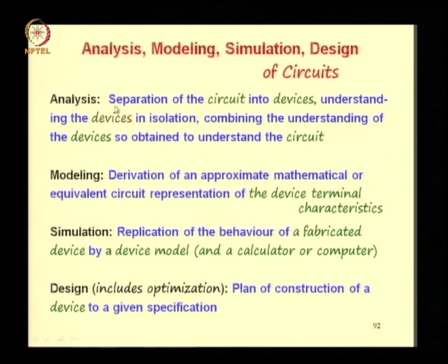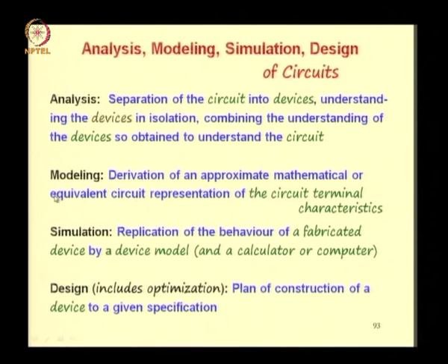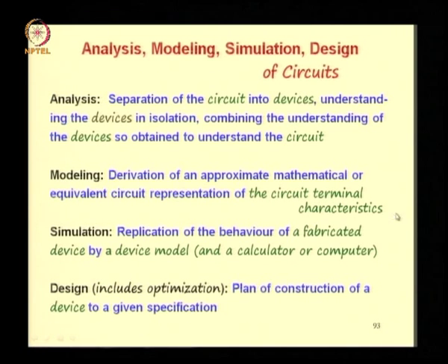So circuit analysis is separation of the circuit into devices, understanding the devices in isolation, combining the understanding of the devices so obtained to understand the circuit. In modeling, you replace the word device by circuit. So circuit modeling is derivation of an approximate mathematical or equivalent circuit representation of the circuit terminal characteristics.